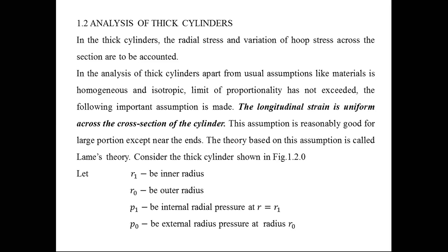In the analysis of thick cylinders, apart from assumptions like the material being homogeneous and isotropic, which you learned in second year mechanics of solids, and proportionality limit not being exceeded, all are important. In addition to that, the longitudinal strain is uniform across the cross section of the cylinder. This is the main assumption given by Lame. That's why it is called Lame's theorem.